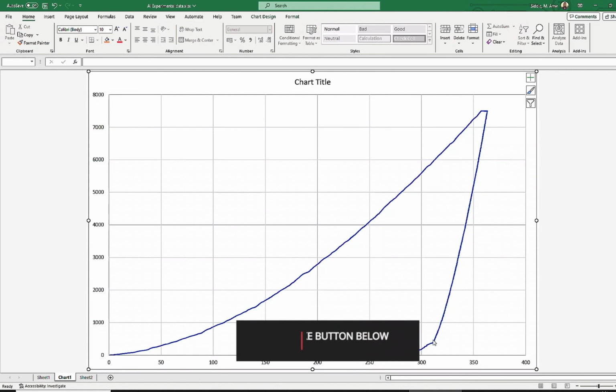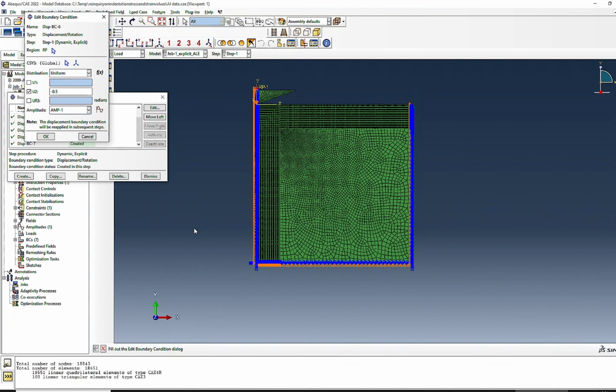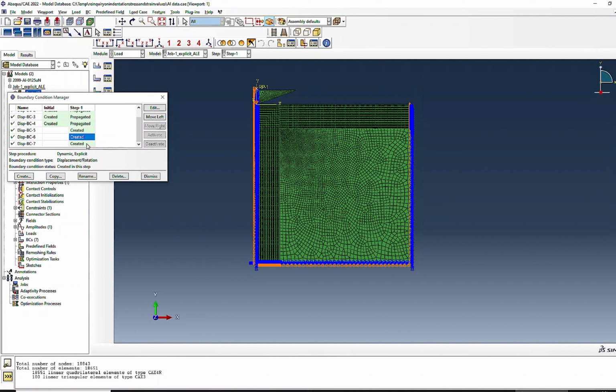And I think this is more consistent because it's going up to 0.35 or 0.37 or something, most probably. It's around 0.362 is a max. So 0.365 or something like that should be okay. So we can change this to 0.365 if everything is in micrometers. And we have to look at the amplitude as well, because that has to go down and then go up as well. So we will check that later.